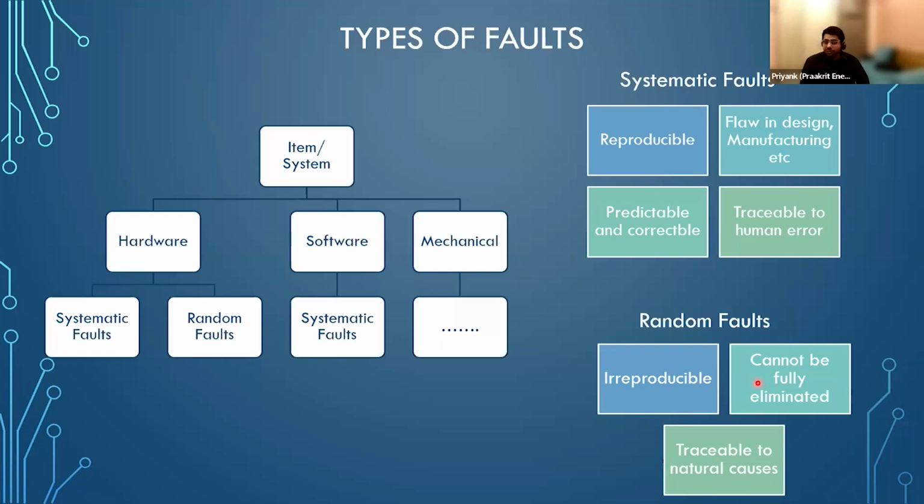You can never achieve zero. Perfect safety does not exist. You just need to take it to a level where it's adequately meeting certain given standards. And this is a very important thing to remember, that random faults cannot completely be eliminated. You can design systems to mitigate against them so that they don't become dangerous. And that is the entire point of hardware safety.